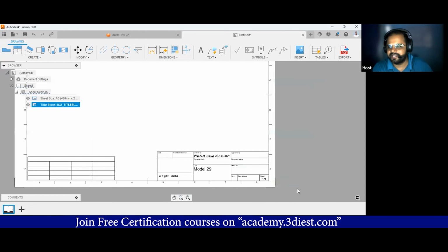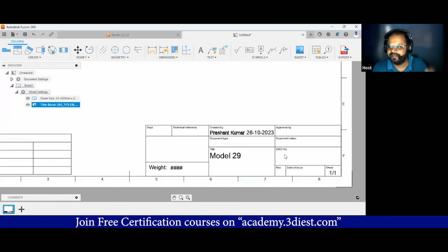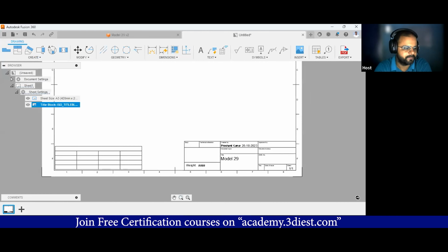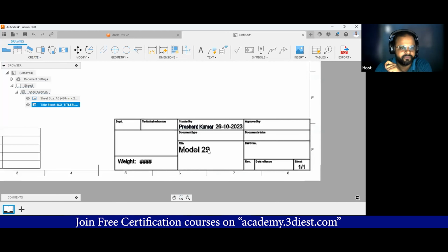But in title block, these are the things that I had talked about: the drawing title, drawing number, the revision date, then the company information, weight, and material. This is where the basic information that has always to be there inside your technical drawings title block. Now let's move on to other things like there are few more stuff like you had to specify the system of units that you are following, like whether you are following feet, millimeter, or inches. That always has to be there. Here we don't have such information, but has to be there.